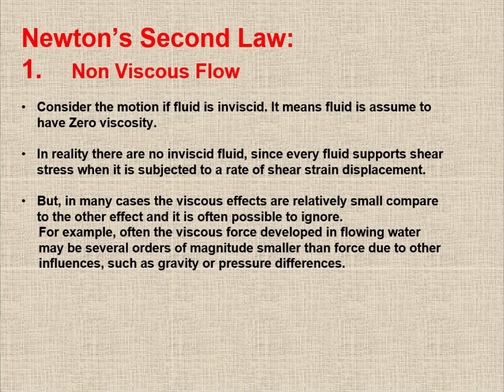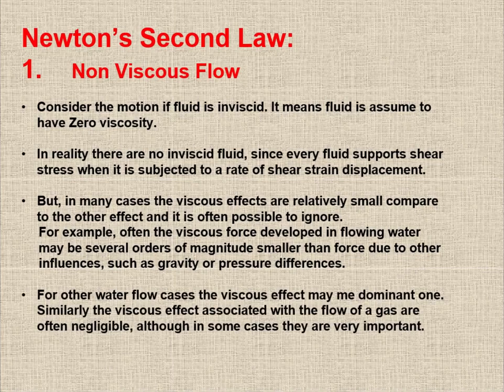For example, often the viscous force developed in flowing water may be several orders of magnitude smaller than forces due to other influences such as gravity or pressure differences. For other water flow cases, the viscous effect may be the dominant one. Similarly, the viscous effects associated with the flow of a gas are often negligible, although in some cases they are very important.